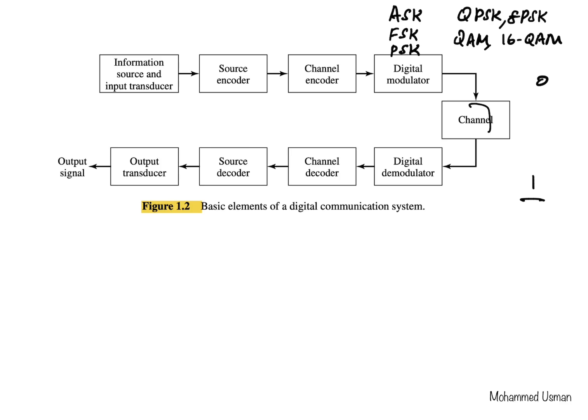And finally, when it passes through the communication channel, the received signal is going to be corrupted by the various distortions that can occur in the channel. The first is the signal will get attenuated, which is the loss of signal strength as it propagates through the channel. It could be affected by additive noise, which is random, and there could be multipath propagation, because of which there could be fading, and there could also be interference from other users' signals, which has got mixed up with our signal.